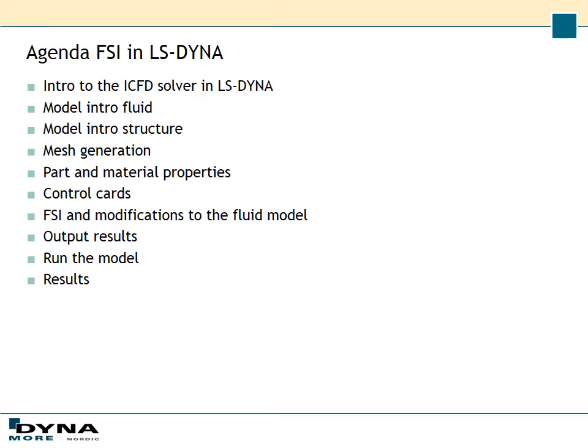First we're going to talk a little bit about the ICFD solver, which is the CFD solver in LS-DYNA. Then I will give a brief introduction to the fluid model, and then I will go through how to set up the structure model. And after that we're going to define the FSI connection and do one small modification to the fluid model. And then I will go through how to post-process the results.